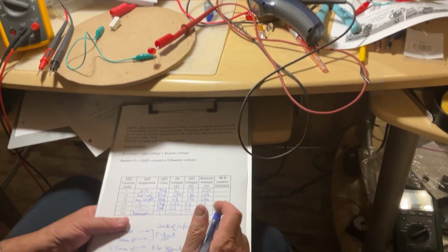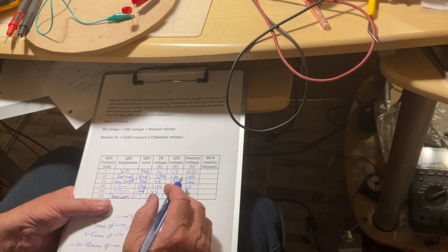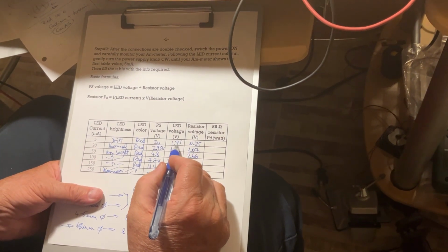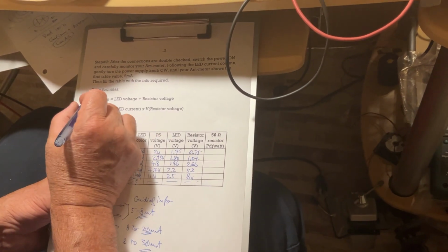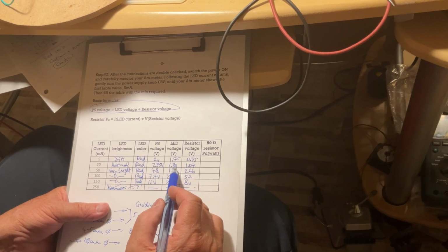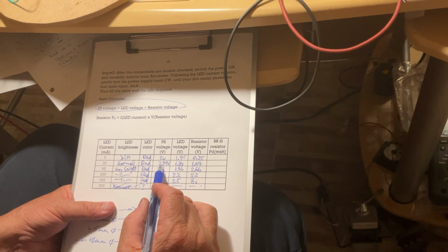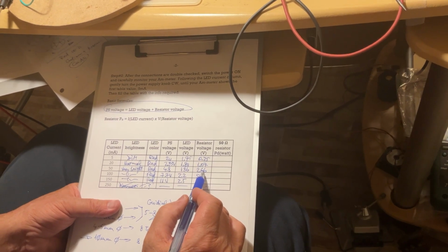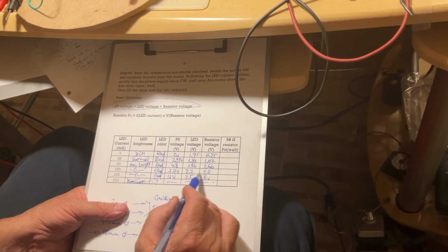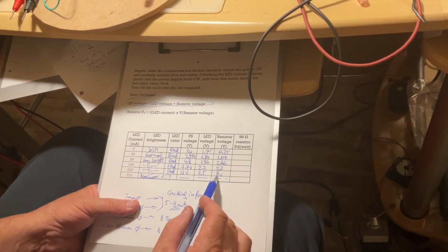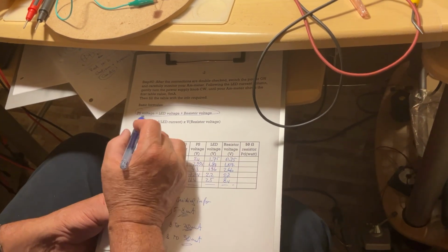Now, how do we interpret the measurements? Because we took approximate measurements, we can take a look here. If it was 1.75 volts, 1.75 plus 0.25, it was 2 volts. So obviously, respecting the basic relationship here. Similarly here, approximately 3 volts, 1.80 something plus 1.1, 2.9, approximately the same. 4.8, here 2 volts, plus 2.66, 4.66, not far from 4.8. 7.7, 2.2 plus 5.2, 7.4, so it's not far. And here 2.5 plus 8 is 10.5, not far from 11. So we can say with the approximate measurements we took, the relationship is respected.